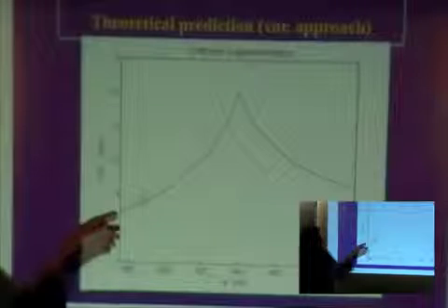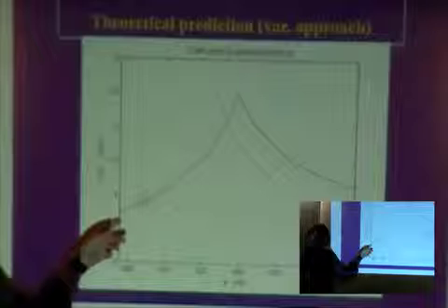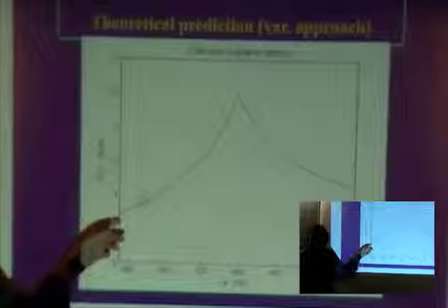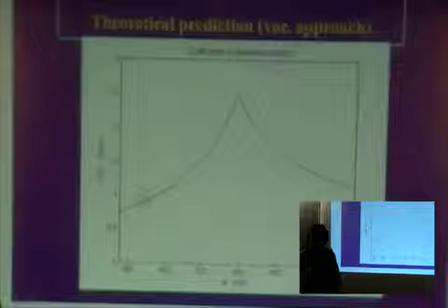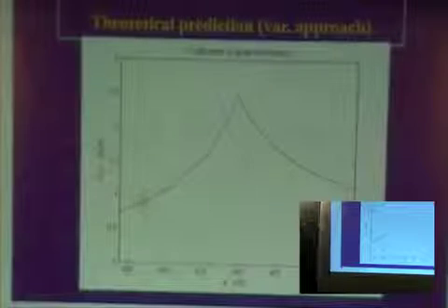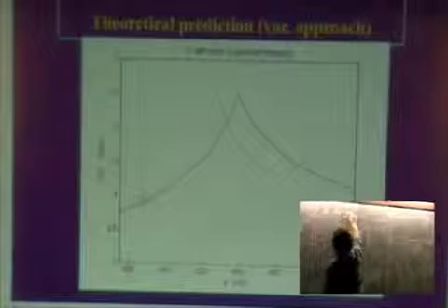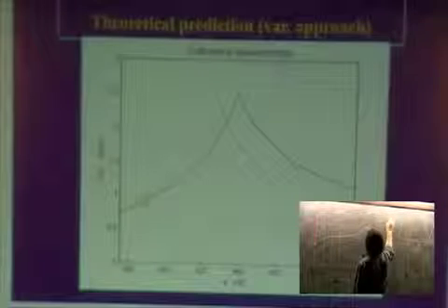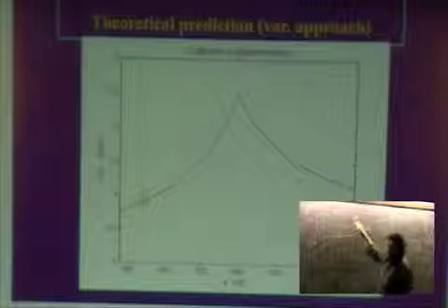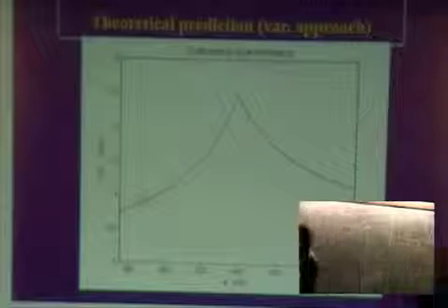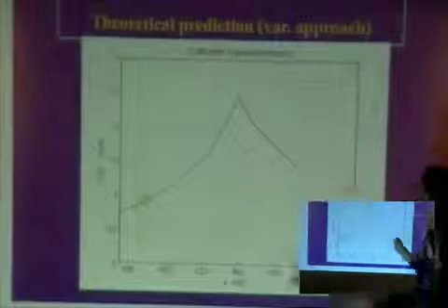And as you can see, this is an optimally designed damping. That is exactly what cannot be done by the usual damping systems. So we have a peak of damping in correspondence of the natural frequency of the system. This is just the damping. The equation of motion can be thought of like this. I'm speaking about this coefficient that is frequency dependent, as you see, a convolution integral. So you have a peak.